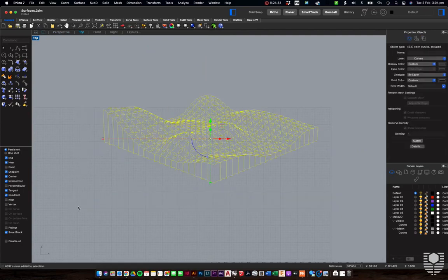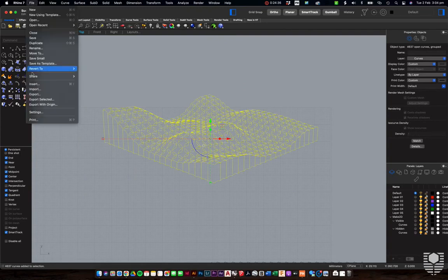So what you'll do is you'll select it, just the parts you want. Then we're going to go over to export selected, not export. Remember, export is going to take everything and it's going to be a real nightmare to edit later. So we just want to export selected, and that's always just going to be our make 2D. So we're going to make 2D first. Even if we're in plan view, we make 2D. That way we're only ever dealing with one line in any given direction.